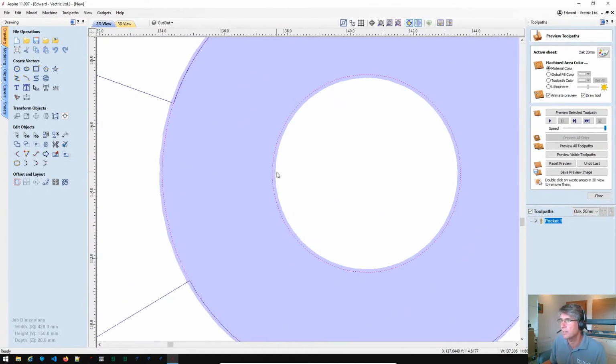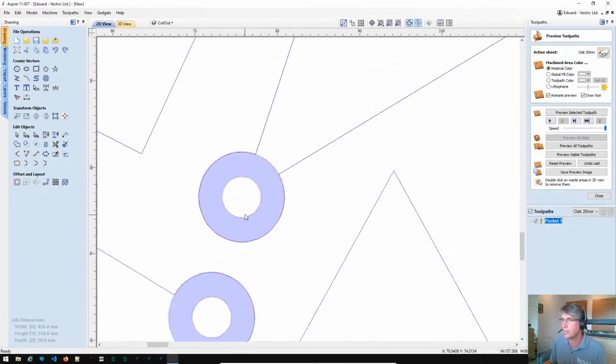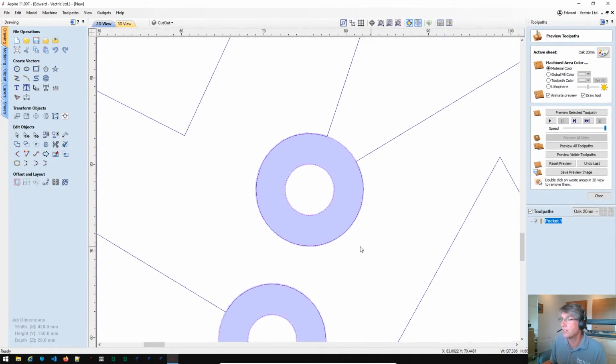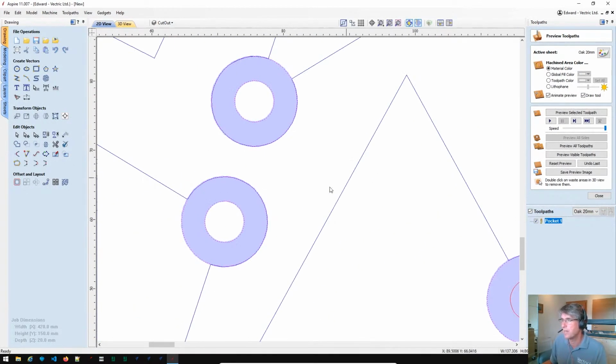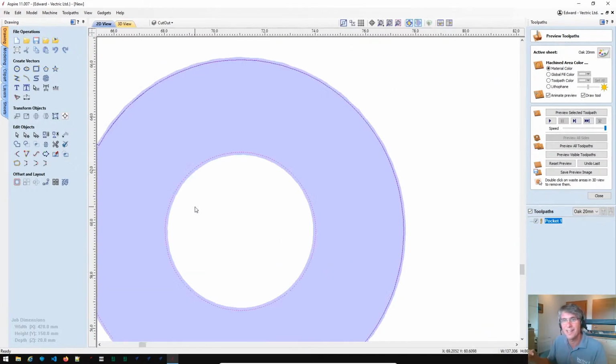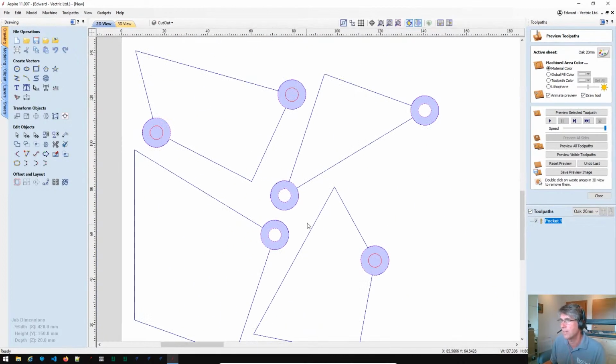That gives you a much better view, I think, of what you're overcutting. It's very hard to see anything relating to this in the 3D view. So you can see here, I'm making my pockets slightly bigger so that the hinge regions around here will be slightly overcut, and the pins, because they're overcutting inwards, if you like, will be slightly smaller than 6mm, and hopefully that will give me a nice fit. So that looks good. Okay, so that's the pocketing.